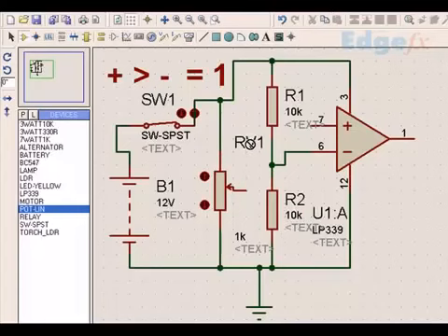And now I connect it. If you are getting confused, let me take it at an angle so that you will not be confused. Now this potential divider, which is a little above 6 volts, I have connected to the plus terminal, and this, being 10k and 10k, is bound to be 6 volts.